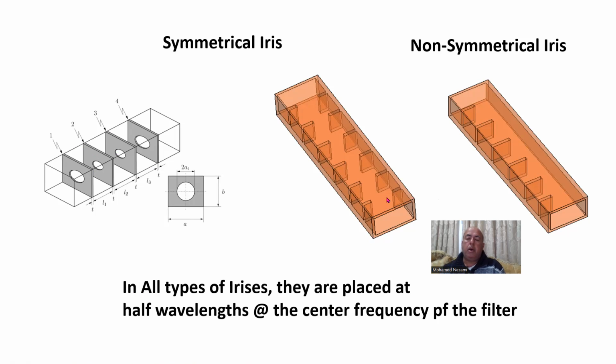And this one here, a lot of times you see it implemented by cutting an existing waveguide. You just cut through it, insert sheets, and solder them inside. So you don't need CNCing on this one. You just get a standard waveguide, make a slot for these metal posts, insert them in, and enclose the slit.